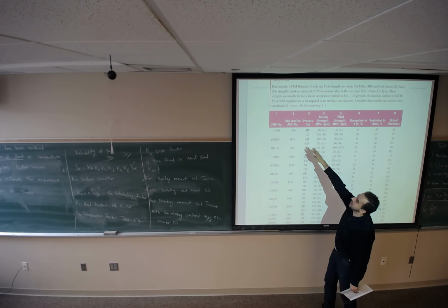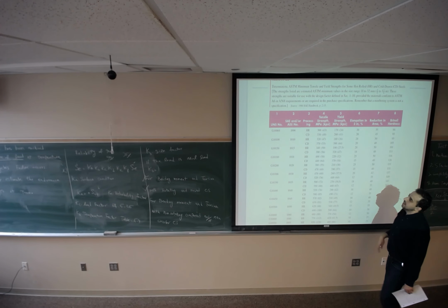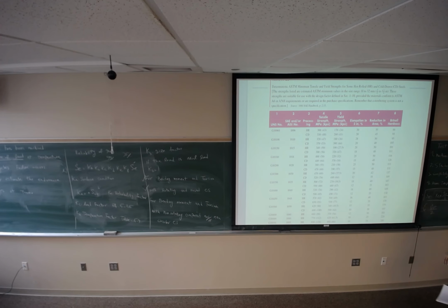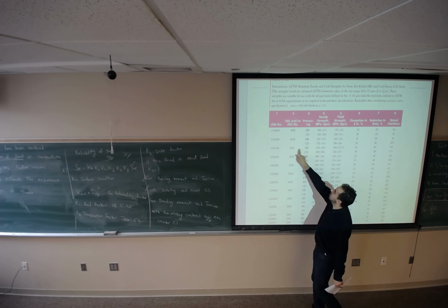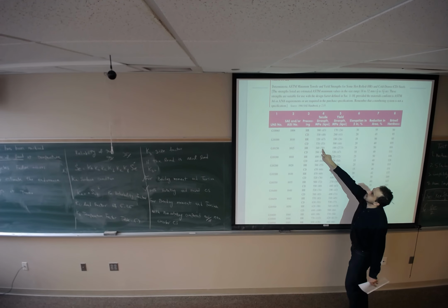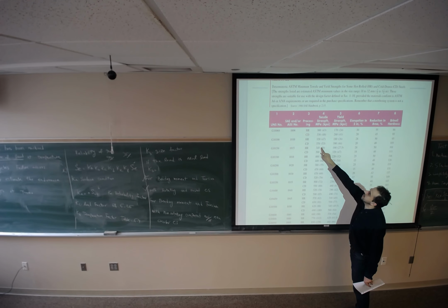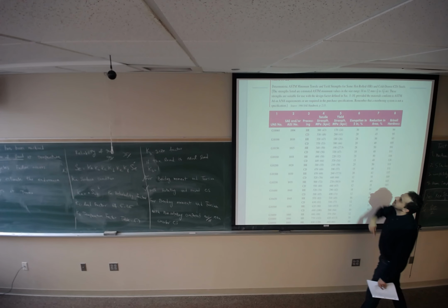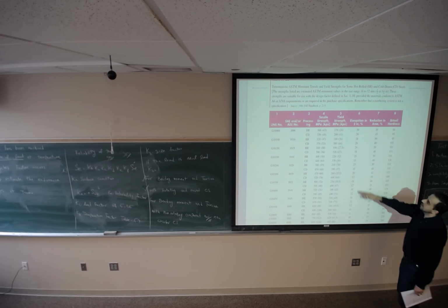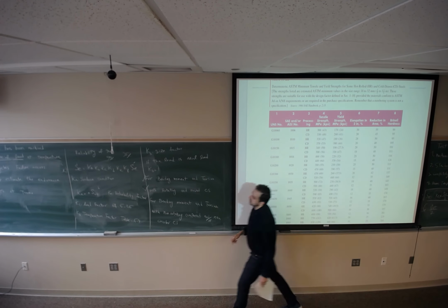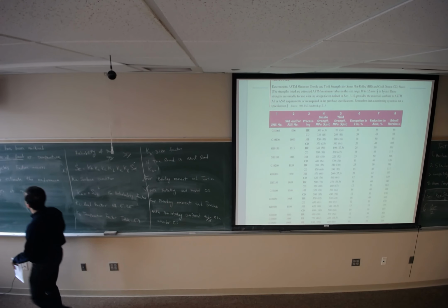Table A24 is going to have the strength of the material for the steel. So 1015 is here, hot rolled. It has S ultimate of 340 megapascal or 50 kpsi, and the yield strength of 190 megapascal and 27.5 kpsi.